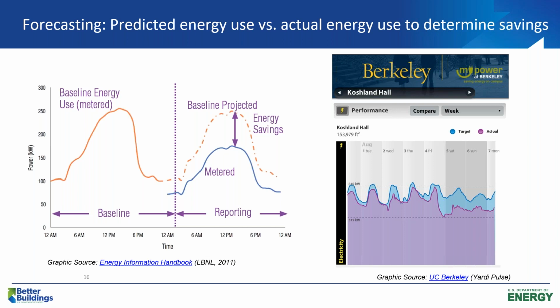But these tools have this all embedded, so you can very easily create these baselines, reset them when you need to, and so forth. You can also, and not just M&V, you can see when things are going out of whack. You can set your baseline to a commissioned operation, and then when something goes, let's say 10% outside of the prediction, you can get a flag.